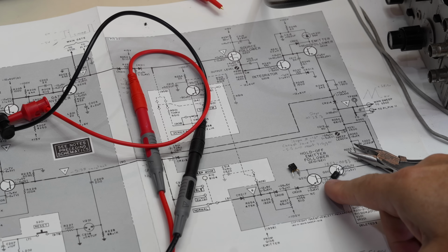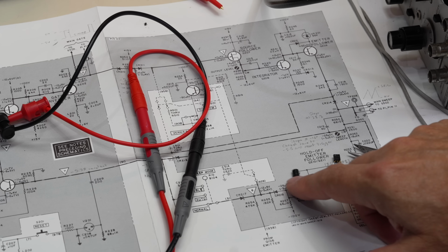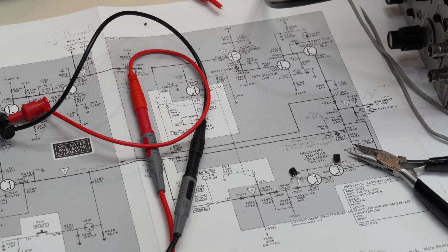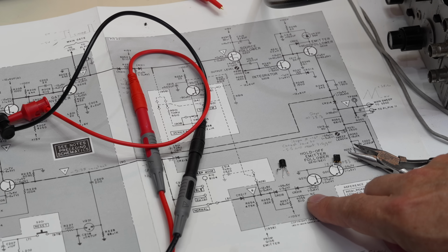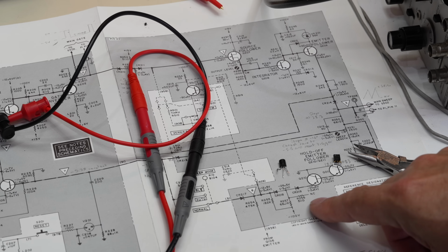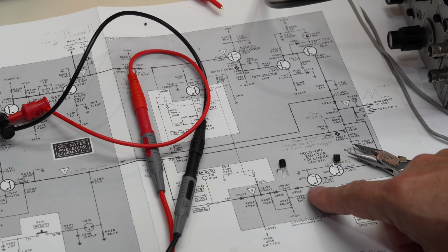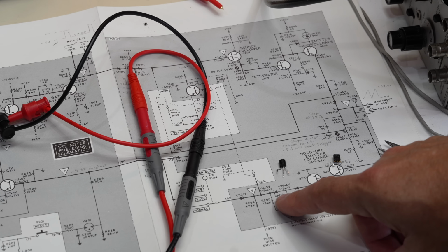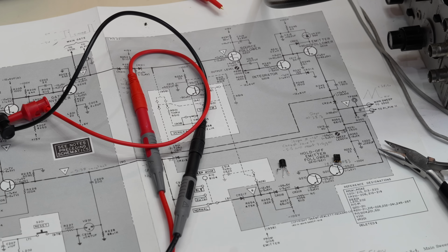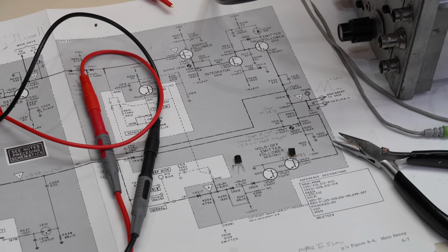So I took the transistors out again, and it's as before: Q210, the one that died before, blew up again in a similar way. It's an open now, so it's an overcurrent. So something here causes terrible pain to this transistor. That resistor burned out. This diode is not a diode anymore, I just checked it. Okay, never a dull moment. Dang it, we were progressing for a while, now we're regressing again.